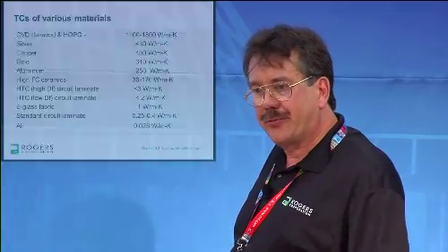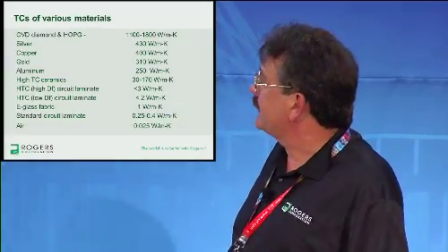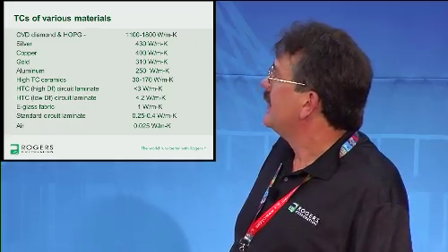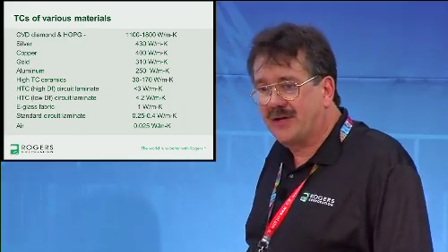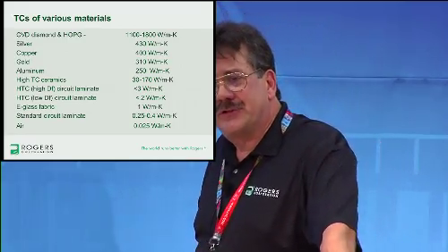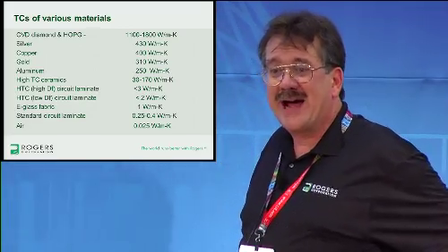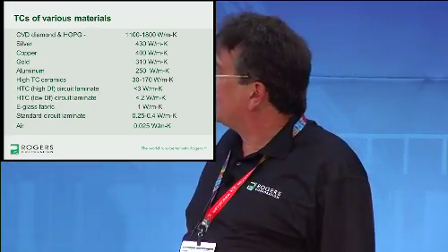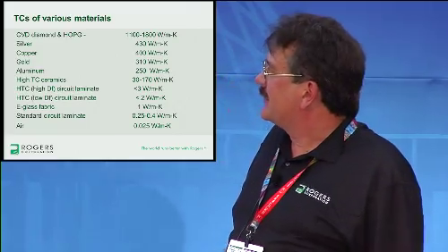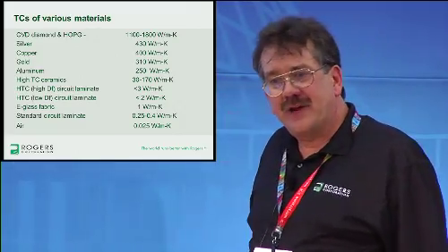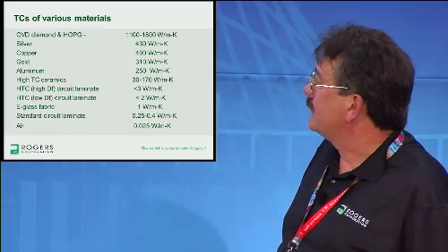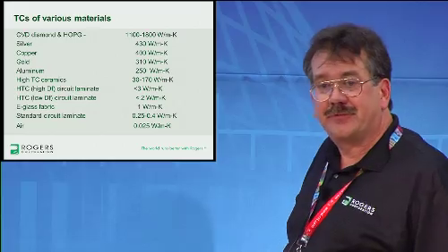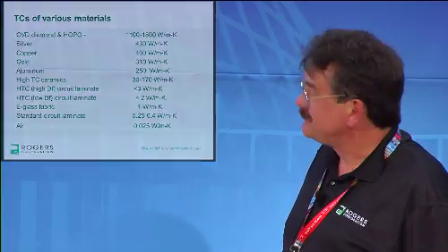For insulator materials, the highest thermal conductivity dielectrics are ceramics. They're in the range of 30 to 170 watts per meter K. And when we get to organic composite circuit substrates, you'll see that there's an order of magnitude or two drop in what we're calling high thermal conductivity. But as I said, it's relative, because standard circuit laminate is often half an order of magnitude or an order of magnitude lower, and all of it is very high compared to still air.